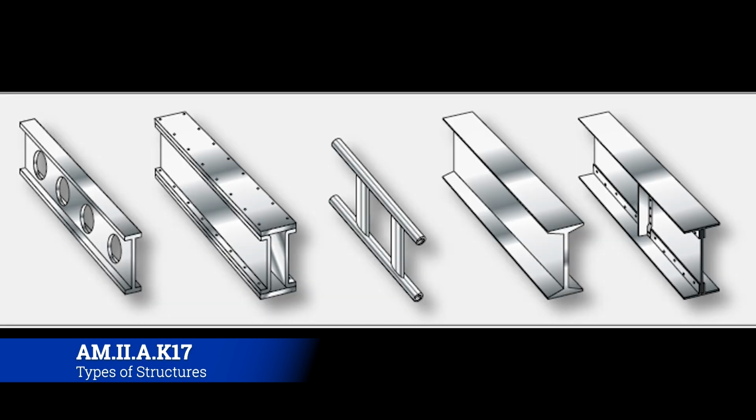All right, here's some examples of what spars can look like. The one on the left is probably the most common that you're going to find. Those circular holes that are cut out of that I-beam like structure are called lightening holes. They literally just make the aircraft lighter. It doesn't really compromise that much of the structural integrity, but the weight savings is pretty substantial. So it's a very common and popular design.